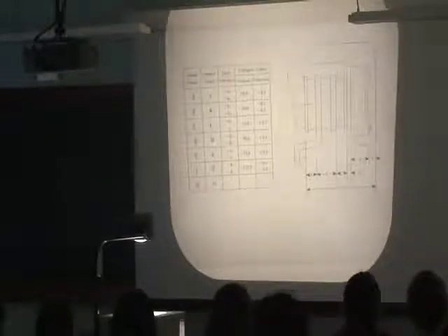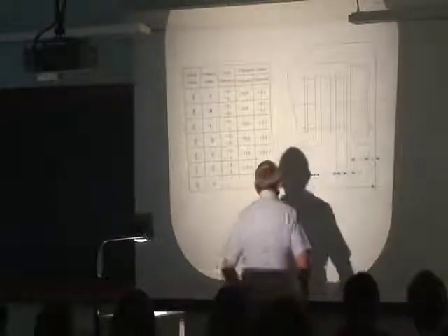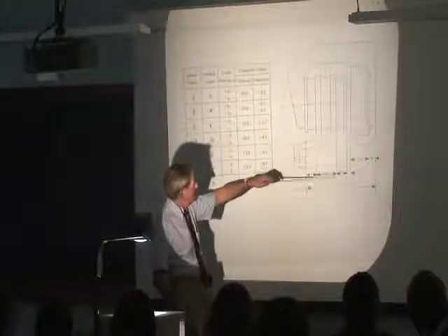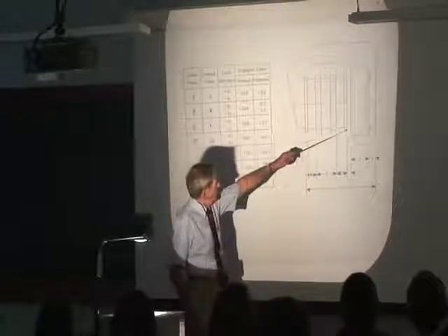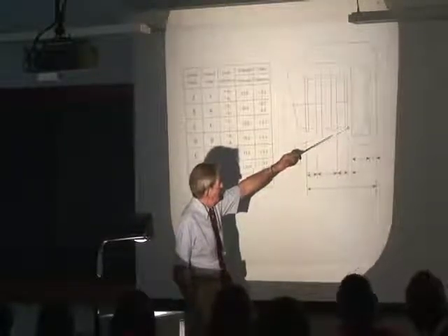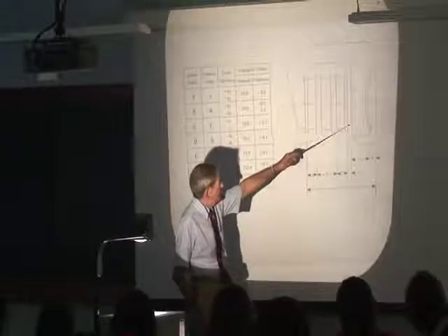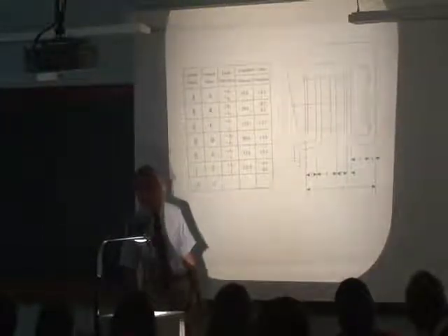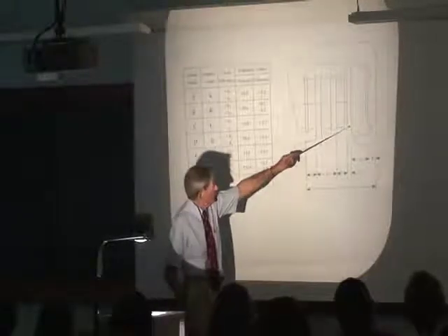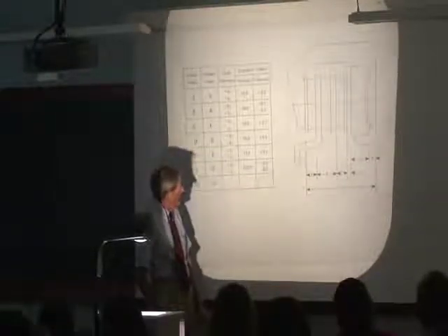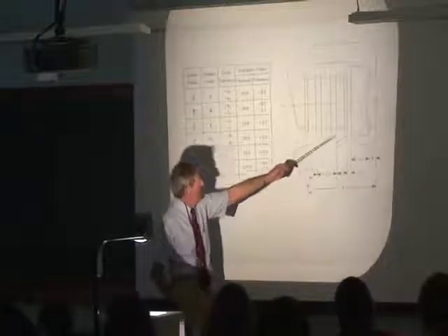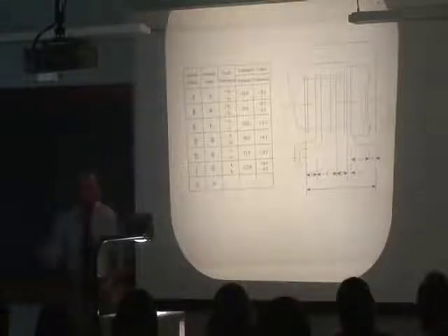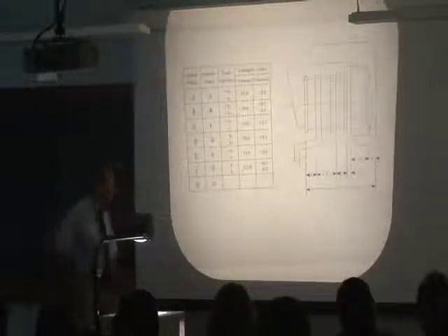These various components have dimensions, and the variability in these dimensions has to be controlled well enough so that you can be sure this gap is never negative. A negative gap means there is no clearance here whatsoever. And you won't be able to put the brake together unless you have some clearance. And the brake won't operate right unless there's a little gap there. But you can't have the gap too big because you'll run out of range of the actuator. And so there are limits on how much variability you can accommodate.